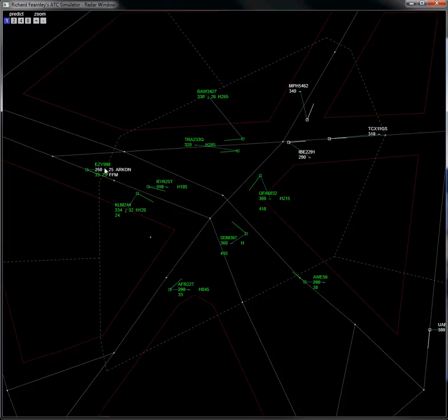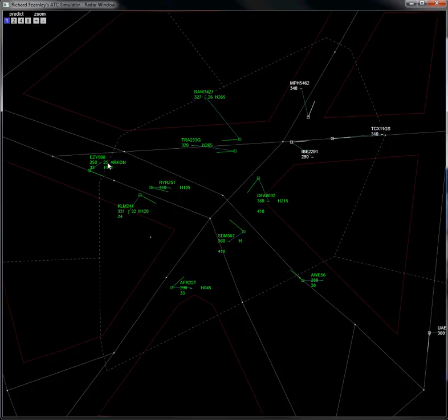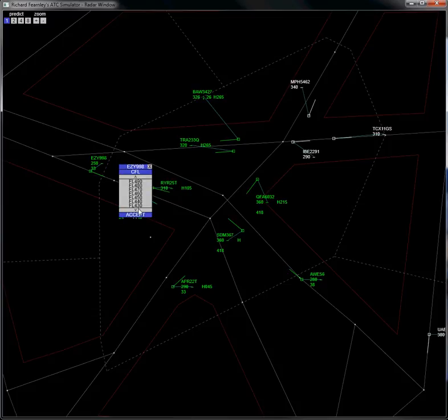An aircraft entering my sector, EZ998, I assume him, and I can issue him climb. The Cactus 56 is not affecting him. These two airways are deemed longitudinally separated, so I will issue the aircraft's climb to its final flight level of 330. I went a bit too fast there.